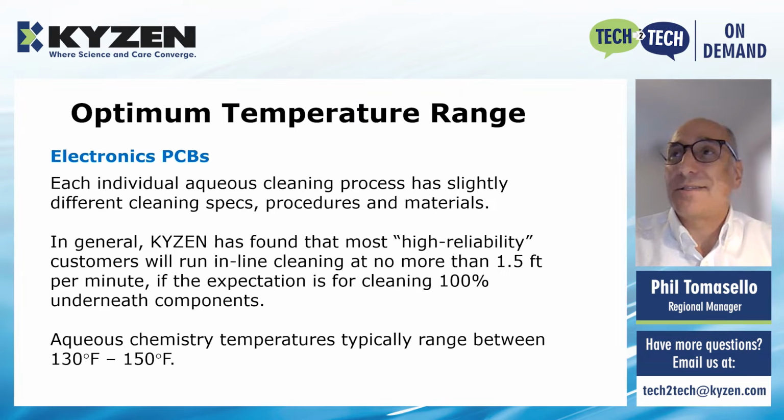But in general, KaiZen has found the most high reliability customers are running inline cleaning at no more than 1.5 feet per minute, with the expectation of cleaning 100% underneath those components. And the aqueous chemistry temps typically range in the 130 to 150 Fahrenheit range.